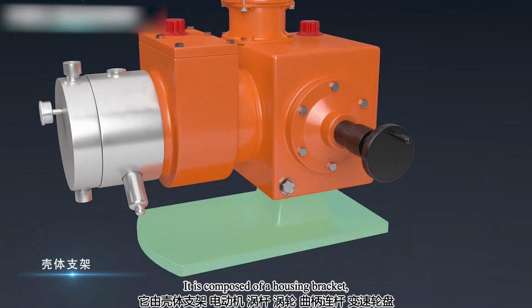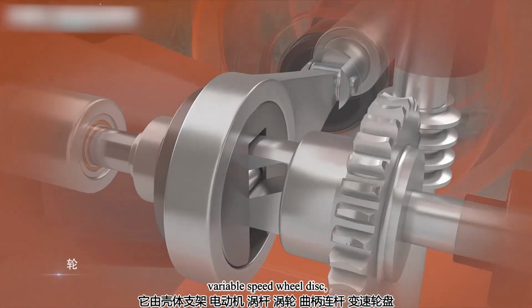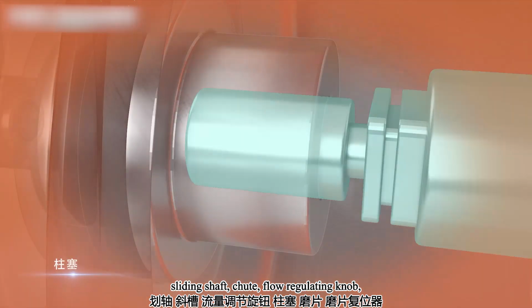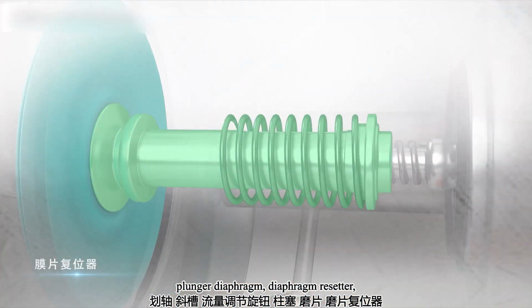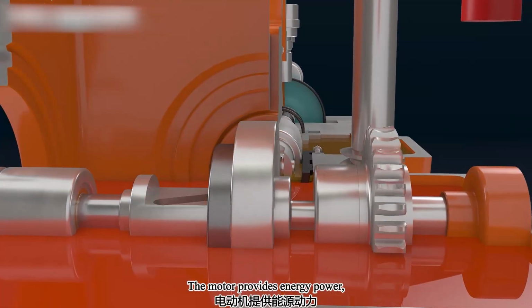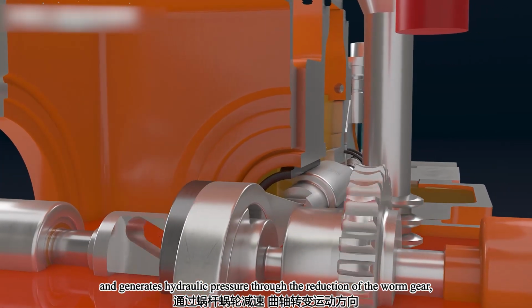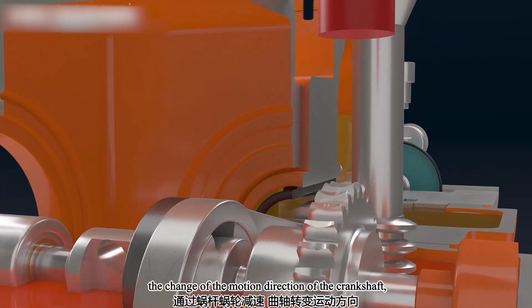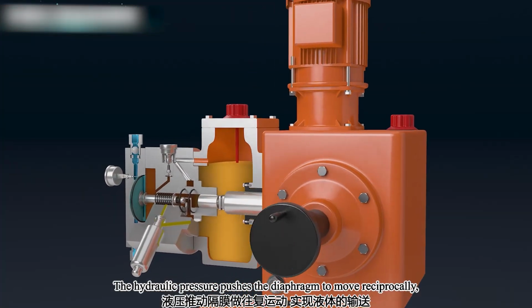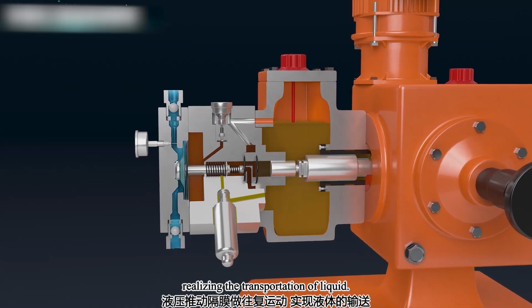It is composed of a housing bracket, motor, worm, turbine, crankshaft connecting rod, variable speed wheel disc, sliding shaft, chute, flow regulating knob, plunger diaphragm, diaphragm resetter, inlet check valve, outlet check valve, etc. The motor provides energy power and generates hydraulic pressure through the reduction of the worm gear, the change of the motion direction of the crankshaft, and the reciprocating motion of the plunger. The hydraulic pressure pushes the diaphragm to move reciprocally, realizing the transportation of liquid.